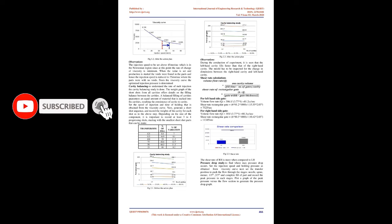Cavity balancing. To understand the rate of melt injection, the cavity balancing study is done. The weight graph of the short shots from all cavities offers details on the filling balance between the cavities. A balanced filling of cavities guarantees an equal amount of material is packed into the cavities, resulting in consistency from cavity to cavity. Set the injection speed and holding time obtained from the viscosity curve.